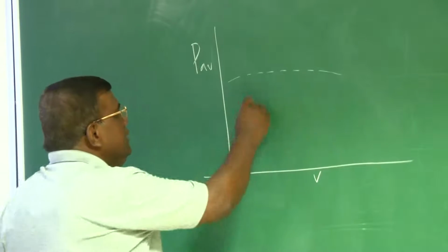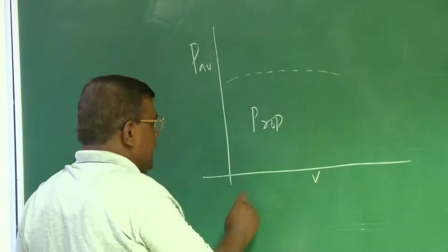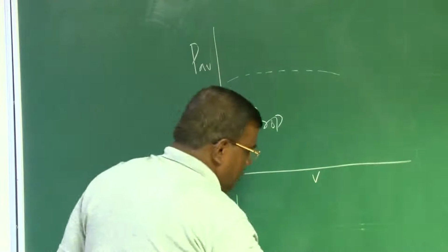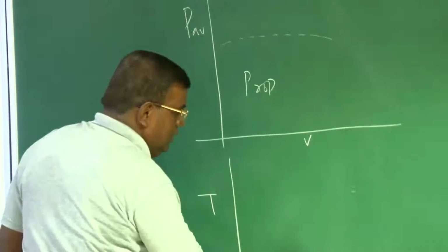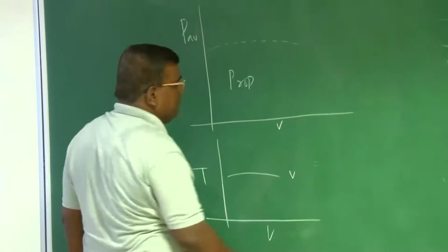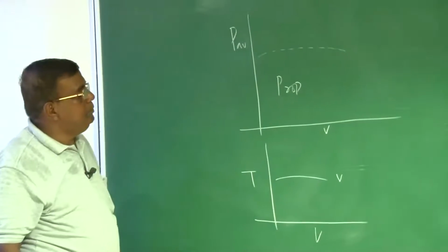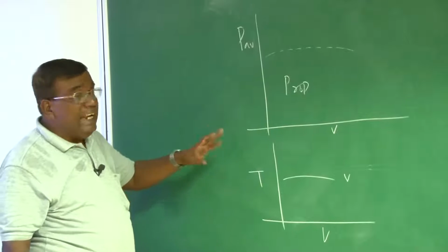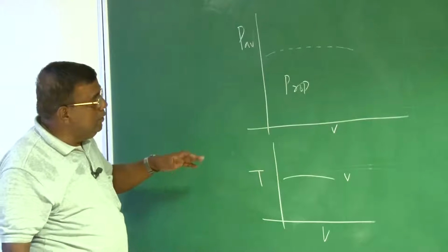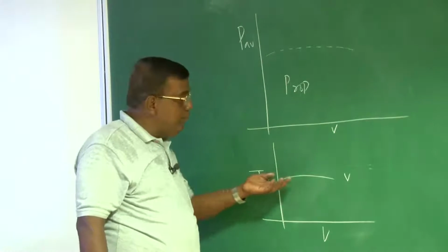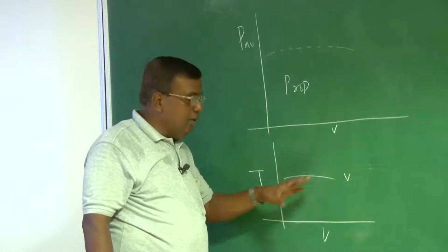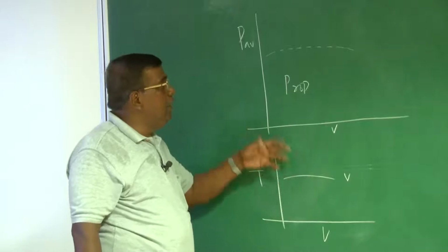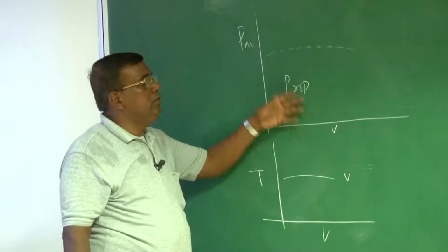For a jet engine, roughly, you can say thrust remains constant with V. So if you are doing dynamic thrust corrections for a jet engine, you can assume it's not going to change with speed, and power is almost constant with speed.